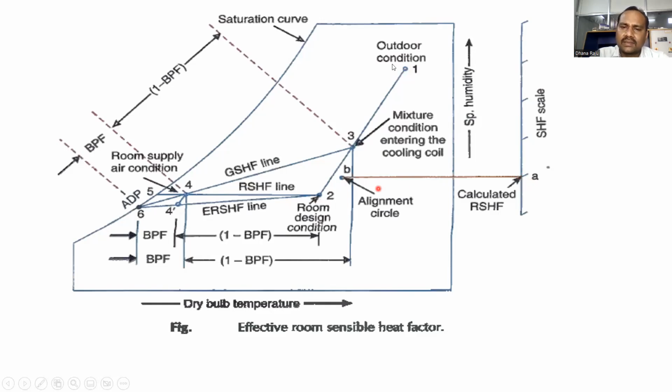And in the psychrometric chart, there is a small circle given which is 25 degrees centigrade, 50% RH. That is called the base circle. So identify B. Then immediately join AB by using a scale. Then, we already located 1 and 2. With respect to line AB, from the point you need to generate a line which is parallel to the line AB.